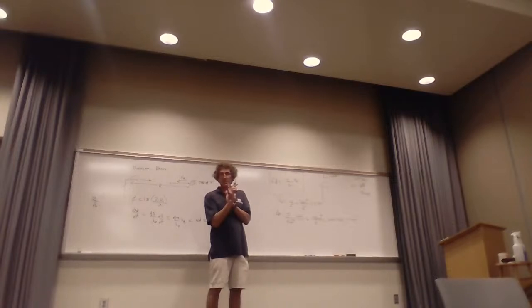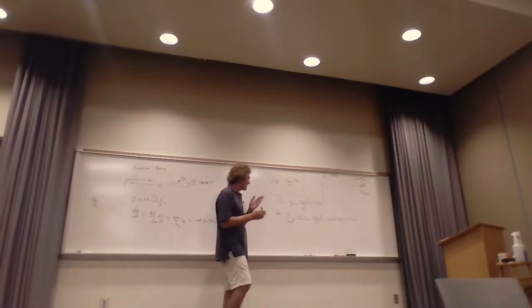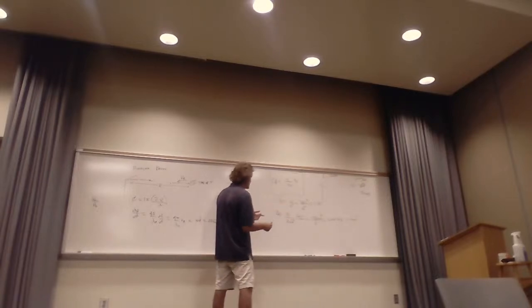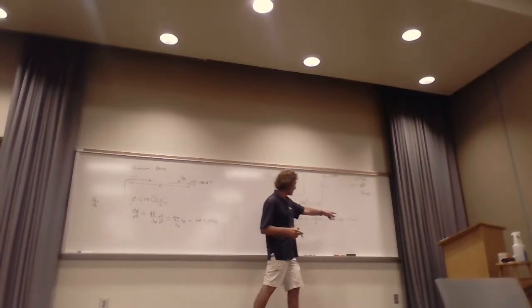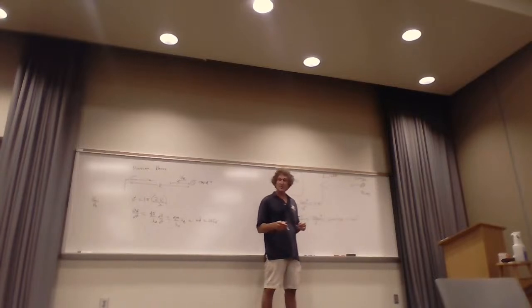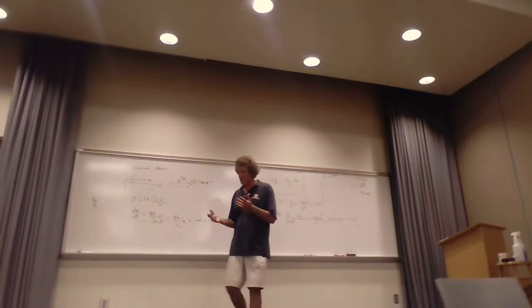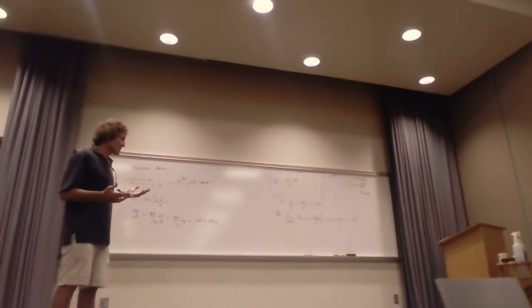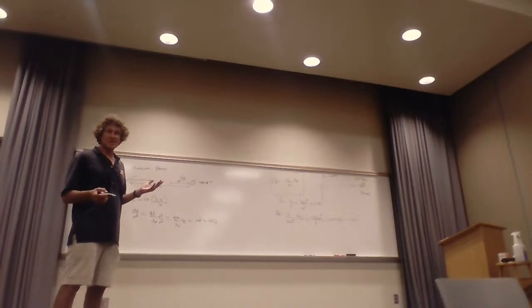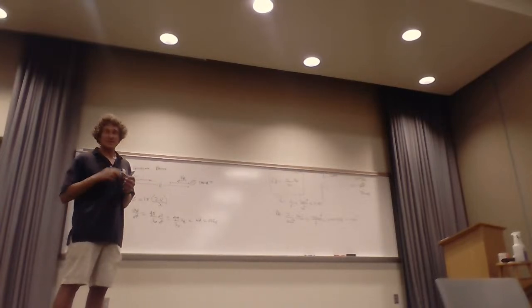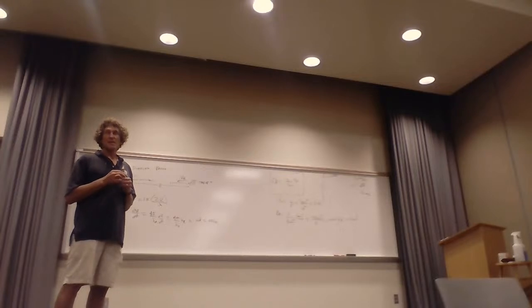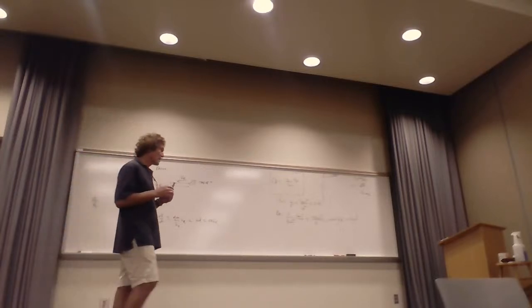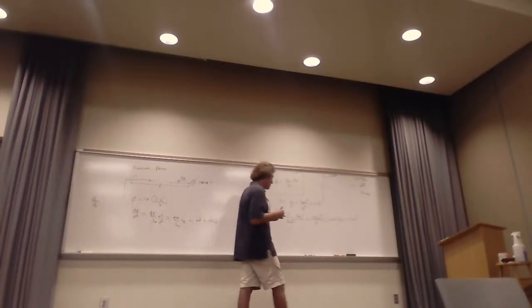You can't see a target there. So when this signal's coming back, it's going to be at 10 gigahertz plus 6,000 hertz. Right? 10 gigahertz is 10 to the 10th hertz, right? You add 6 times 10 to the 3rd to that, it's indistinguishable. The only way they see it, there's a couple of tricks they do. One is coherency, and if I have time, I'll talk more about that.